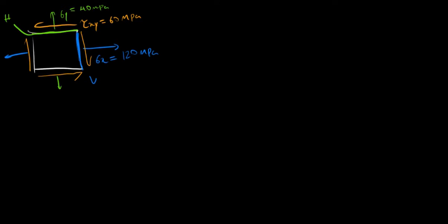Alright. So I'm going to go ahead and draw the Mohr circle. For the coordinate system, the vertical axis is going to be the shear stress, and I'm going to call this one CW for clockwise, and CCW for counterclockwise, and I'm going to explain that soon.